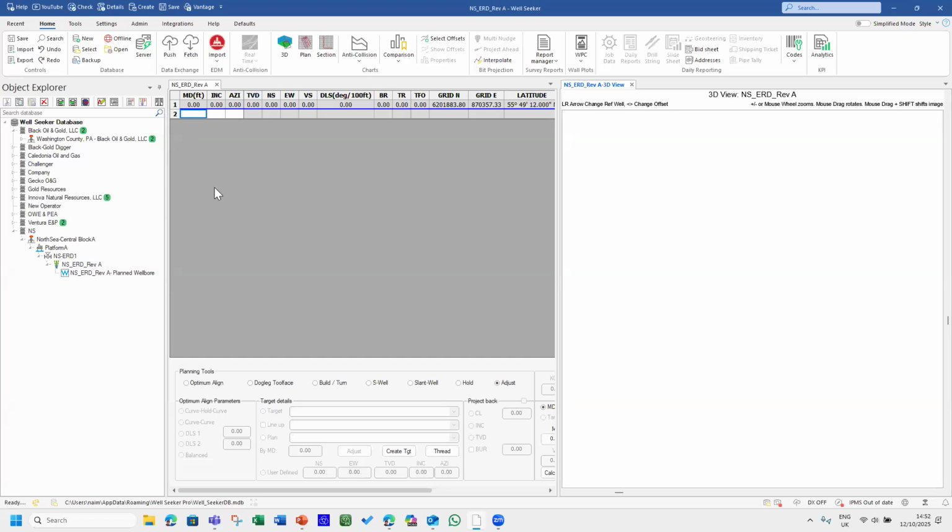Instructions number 1, drill to 500 feet below mudline. The mudline is at 350. Yes, 350 is your mudline. From rig, RTE, rotary table, to the seabed. What's the distance? That's a mudline, 350. It's asking you to drill 500 feet more below that 350. So 0 to 850, it wants you to just hit it straight.